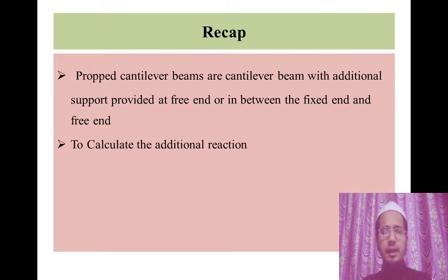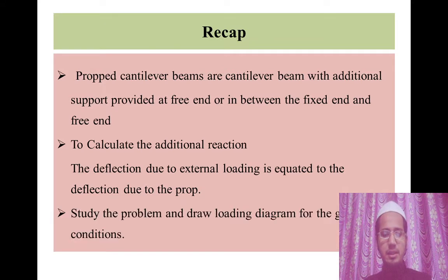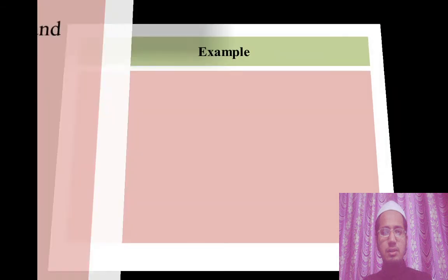So to calculate the additional support we have discussed the procedure, equations and reactions required. The deflection due to external loading is equated to the deflection due to prop. By using this concept we have obtained the equation for the additional reaction at the prop end, and also studied the problem and drew the loading diagram based on the given condition of the problem. So let's start today's session.